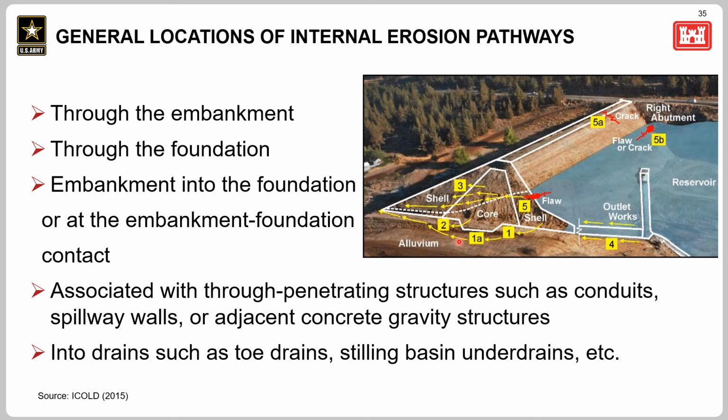Generally, internal erosion associated with through penetrating structures is essentially a subset of internal erosion through the embankment, and it's often seen as concentrated leak erosion. Another location where internal erosion can occur is into toe drains or stilling basin underdrains.